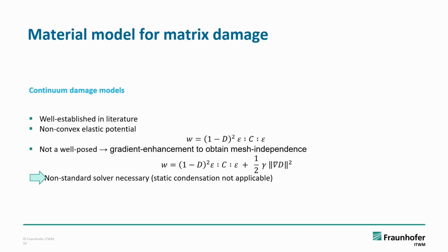There are continuum damage models in the literature which are rather well established, and it's usually based on a non-convex potential as shown here. Non-convex also means that it's not well posed, so we need a gradient enhancement to obtain mesh independence for these kind of models. Also, with a gradient enhancement, we need a non-standard solver to solve a multi-field problem.